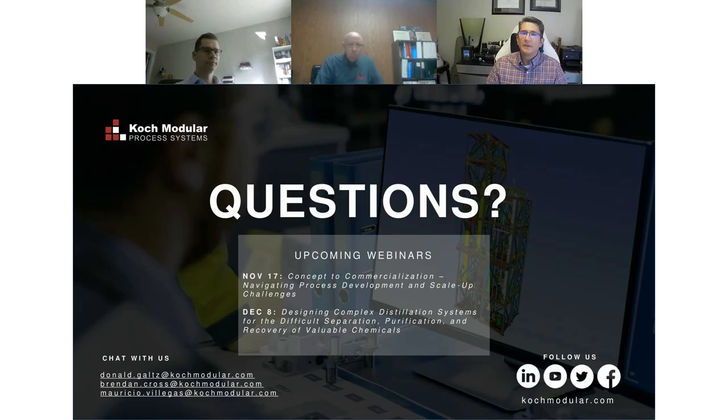Great, thank you. Another question is, are there any technological advantages of vertical extractors over horizontal ones? So there's only one type of horizontal one that I've ever seen commercially. It's the Graesser one we showed in that slide, and it is very, very low capacity, and it only gets a couple of theoretical stages. It's called a rainy bucket.